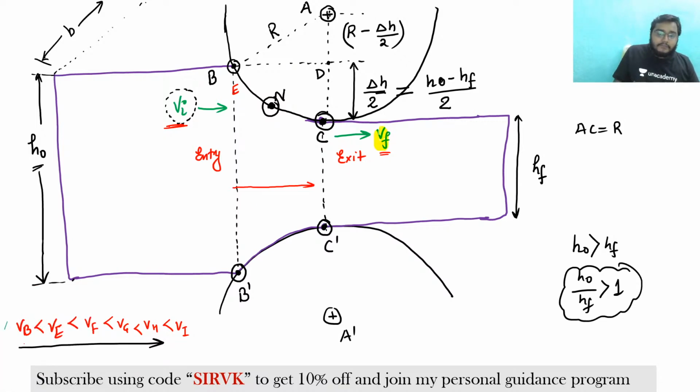So this Vf was the velocity due to which it is moving in forward direction. Now this velocity, that is the Vr velocity. So here the Vr velocity would be acting, and this is the initial velocity. So can I say that due to this initial velocity, since the initial velocity is less, a backward slip would be acting, and the magnitude of this backward slip is written by Vr.